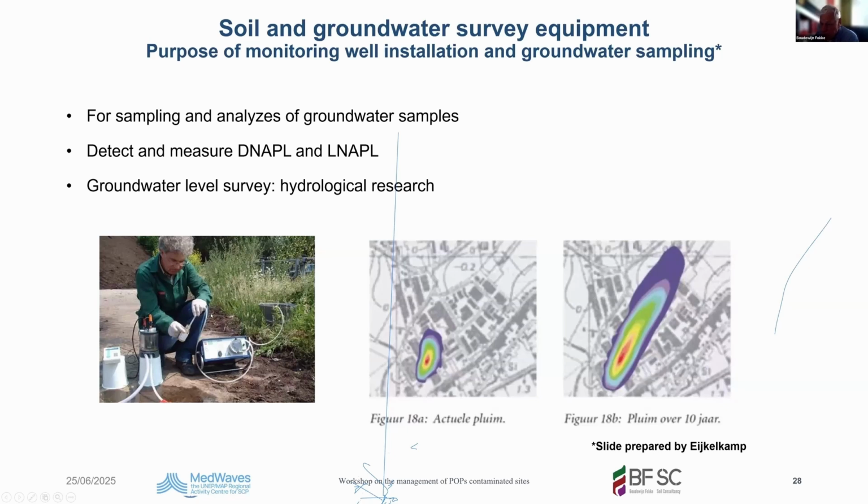Now here is your flow cell, and here's your conductivity and your pH measurement. Here's the well. Here with the slow speed you fill your bottle, and that is the plume you want to discover by installing wells at different distances from the source.